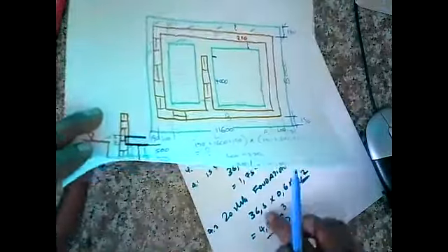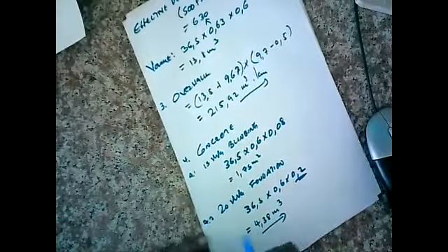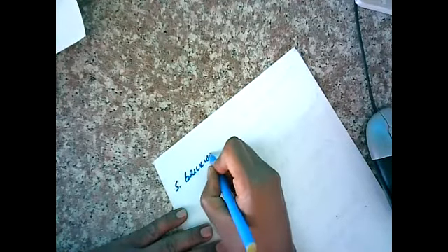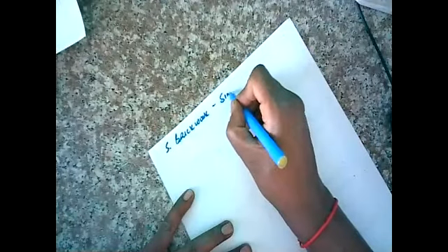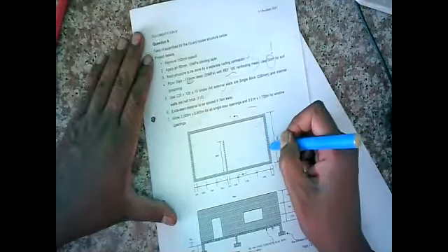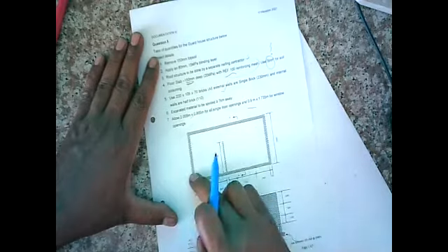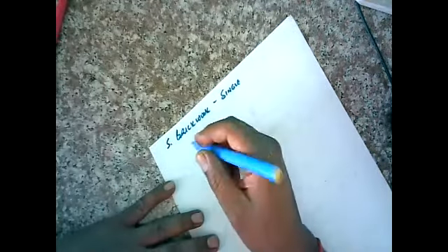All right, we did the floor. Let's look at 5, brickwork. And let's call this single. Why single? Because look at the sketch. This is single brick. This is a half brick wall. So I'm doing it in the sequence of the wall thickness, so we don't forget mistakenly and leave things out.